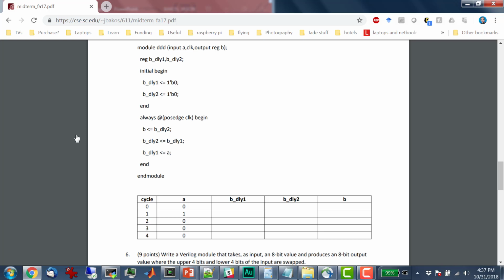The only reason I mention this is it has to do with dependencies. If you get a clock edge and you set something, and then something else uses what you set as an input, what happens? That's the question that's being answered by non-blocking versus blocking. I think that's a concise way to describe it. It's when you assign something according to an event, which is the clock edge.